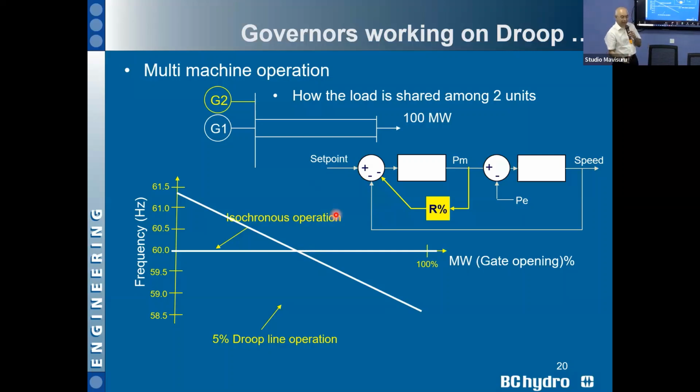When I was leaving Sri Lanka, our peak was about 700 megawatt. Now it is like 1500 or so. How much? 2000. See, so now 700. So assume even 2000, that means it's almost more than double, right? Therefore, for this smaller system, this is fine: one unit making the isochronous operation, which will take the variation of the load, whereas the other unit takes whatever the controlled load.